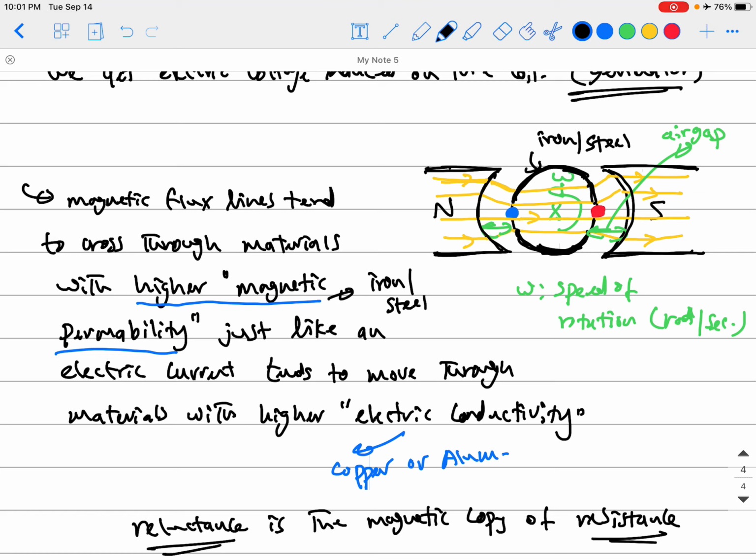And again, because our magnetic field is the medium of conversion, the more magnetic field we have and the more consistent shape it has, the better the energy conversion that will happen inside our machine. Okay, guys, and that's why we are building our machines mostly from iron or steel pieces.